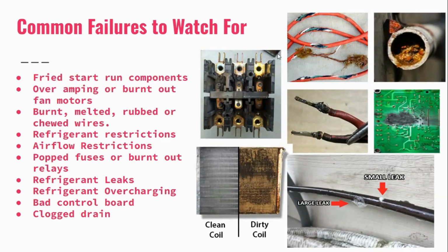There's a coil in the back of it, and these close and stay closed to run the system. If they can't stay closed because there's char, debris, dirt, or rust, then they let go, and the whole system shuts off, because every single component in that outdoor unit is running off of this contactor.